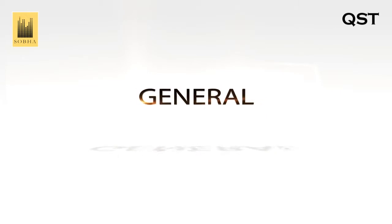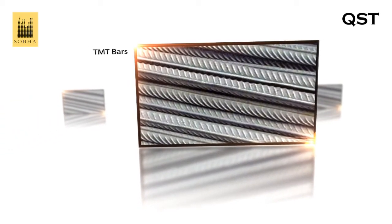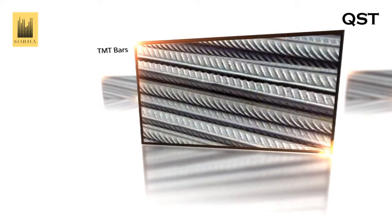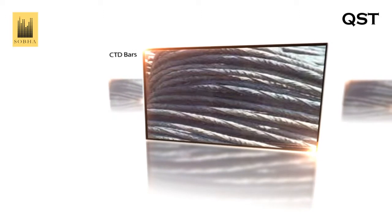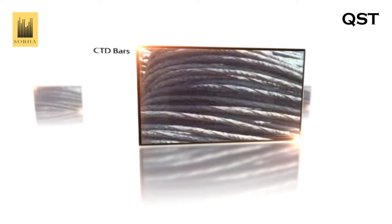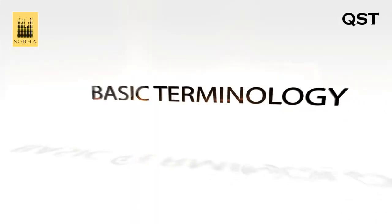The most commonly used types of steel bars are TMT bars, which are thermomechanically treated bars and are manufactured by a special process of quenching and tempering which imparts uniform strength, more ductile and weldable without adding carbon, which will have ribs over it at equal intervals. CTD bars, which is the abbreviation of cold twisted deformed bars, have continuous spiral twisting throughout the length of the bar. Next, we see about basic terminology.